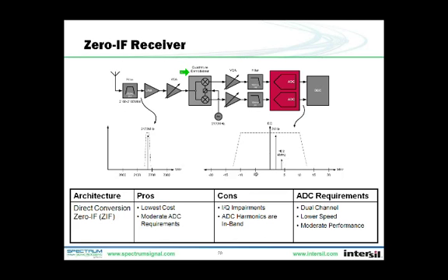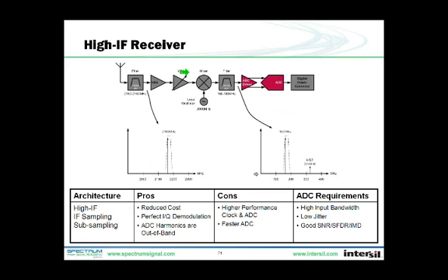This tends to be a low-cost architecture, but mismatch in the offset, gain and phase between the I and Q signal paths, typically from the mixers and filters, can limit the receiver performance. Any mismatch there shows up as an increase in the image frequency and DC, because the RF frequency was mixed to DC.